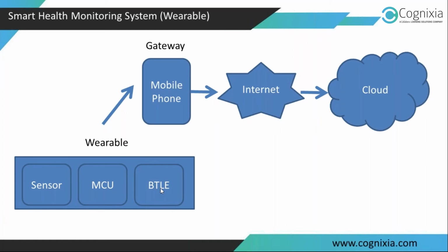Bluetooth Low Energy version 4.0 and now 5 are IoT-friendly Bluetooth versions. BTLE can be used along with a microcontroller, or you can use an external BTLE module, or you can have the Bluetooth Low Energy communication logic circuit available on chip.